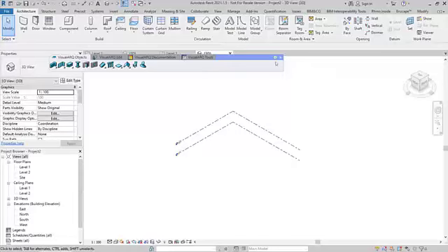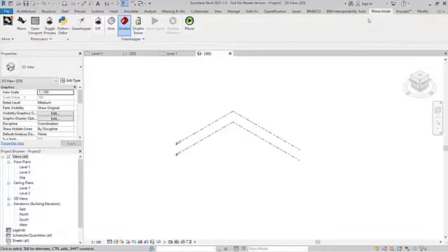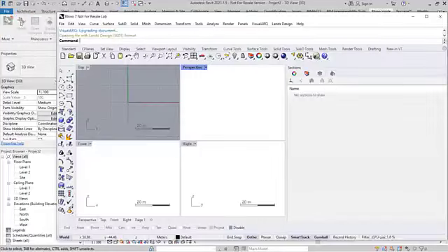And here, as you may know, if we've got the Rhino.Inside plugin installed, Rhino.Inside is a plugin that lets you run Rhino as a plugin of other programs, for example, Revit. So here I already installed the Rhino.Inside plugin for Revit. And when you do so, we've got this toolbar. I mean, first you see some start button here, which enables all these buttons. And now I am able to launch Rhino running as a plugin of Revit.